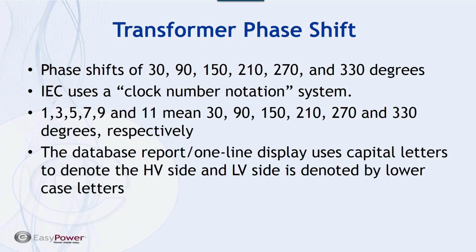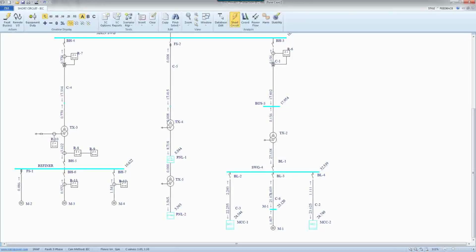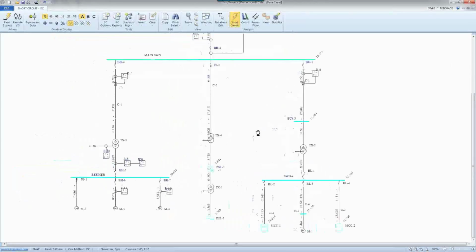see the extent of the work that has been done behind the scenes to include this feature, but this is a big feature we have included here, and it is going to shift the positive sequence components in the positive direction. Let's say if you have a 30 degrees phase shift, your positive sequence value is going to be shifted 30 degrees, your negative sequence value is going to be shifted minus 30 degrees, and of course zero sequence doesn't make it through transformers which have this type of phase shift. So let's take a look and see how it works.